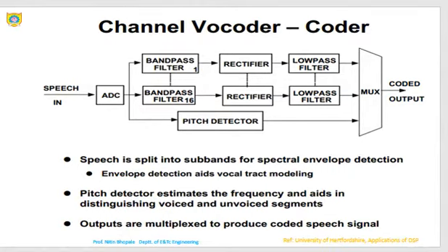In summary, the channel vocoder analyzes the incoming speech signal in three major categories: the speech spectral envelope, then the pitch and the amplitude. The extracted information is then multiplexed and transmitted. Such analysis does not try to preserve the originality of the speech, but tries to compress it without losing the ability to understand it. That is all about the vocoders in the case of the channel coder.